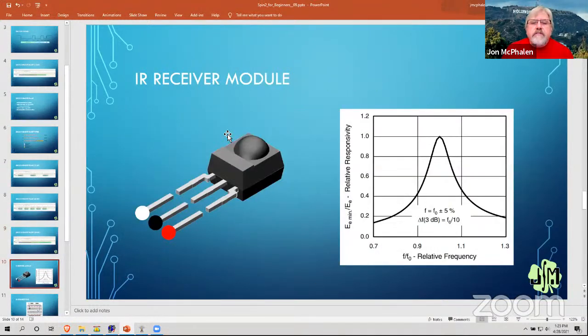Okay, finally, here's that little IR sensor that we were talking about. The middle pin is ground. This pin, if we're looking at the front of the sensor, is our voltage. We're going to use 3.3 volts. It's okay if you hook it up to 5 volts because it's pulled up through a 30K resistor. So that's going to make it safe for the Propeller. And then this is our signal input. So this is pulled high internally when the sensor is not active.